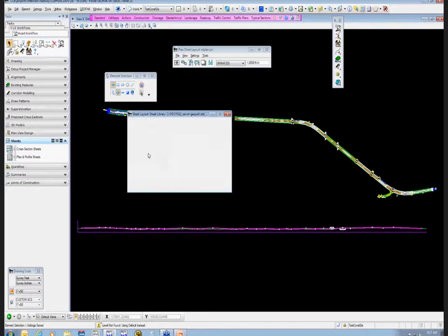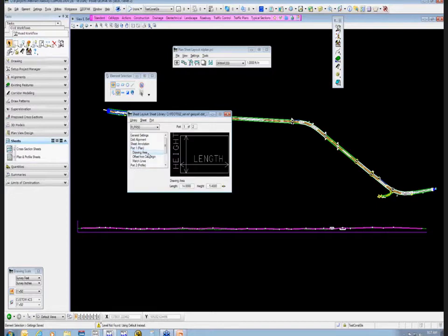Within this plan port, we've got a drawing area which says how big is the area that I have for that port, so it knows how big to create that border. For the plan and profile sheet, we're looking at 14 feet wide and 5.4 feet tall. And this is important to remember in here, how big this is, because it kind of goes hand in hand with the offset from the cell origin.